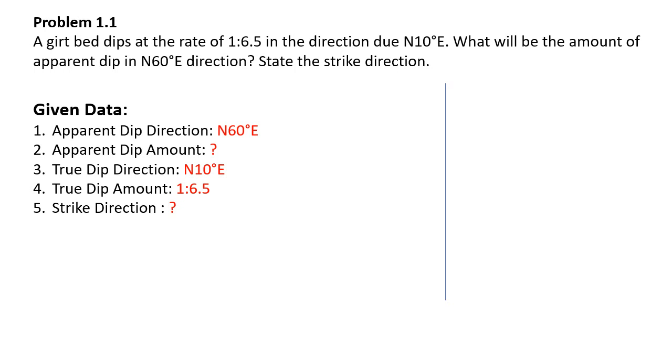So how to solve these problems is, first with exact measurements we have to draw the north, south, east, west line meeting at point O. Okay, are you getting? You have to draw exactly perpendicular two lines with the help of set square. Okay, that is exactly 90°. The two lines we have to draw, that is north, south and east, west direction. That line is meeting at point O, that is the origin or center of that line. Okay, so then first we will mark the given angle.